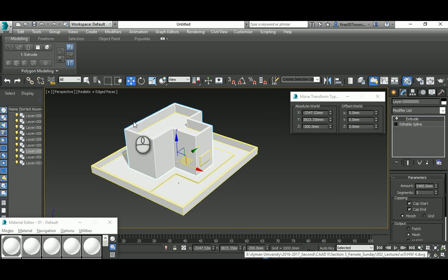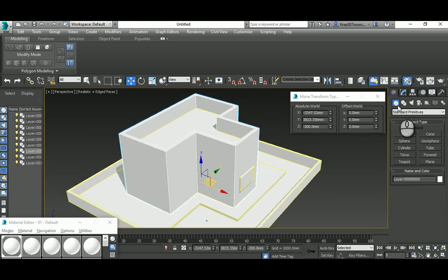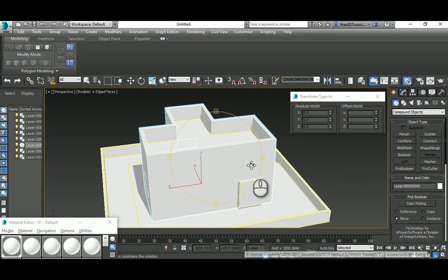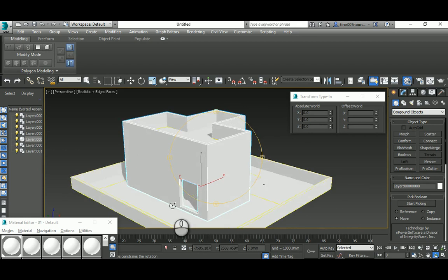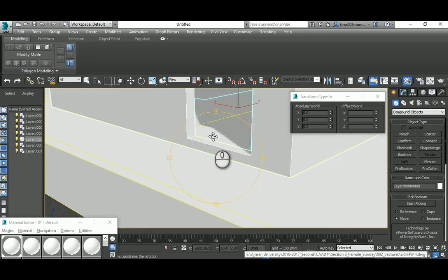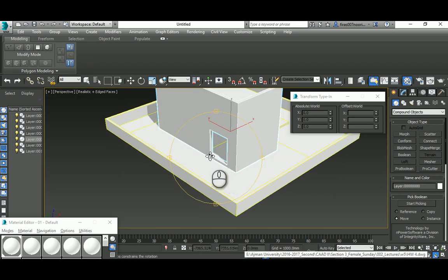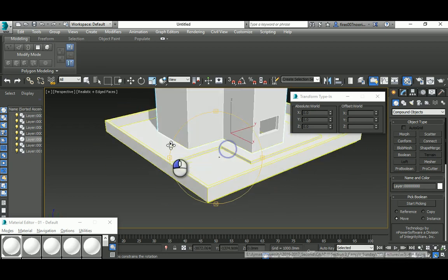Get used to selecting the exterior wall, and then in the create drop-down menu, compound, go ProBoolean, and then start picking, select that guy, and then arc rotate, and then select the door. And that's what I want, really nice. You have to have this threshold because this is lower than that. There is no overhang or balcony or anything, so it's good to keep this distance higher than the inside from the outside, to prevent the rain from getting inside.